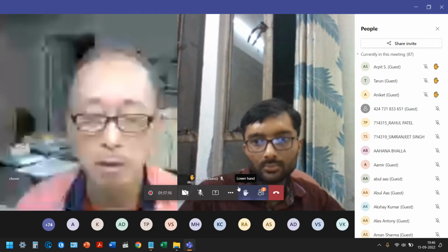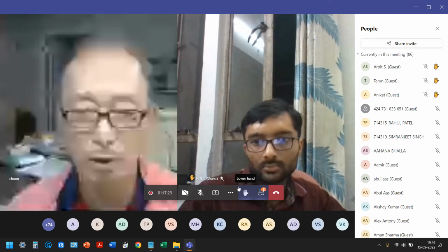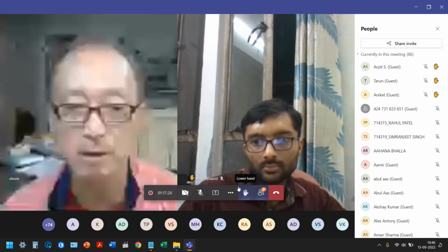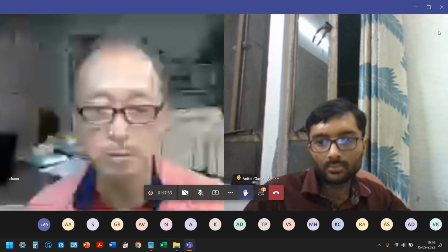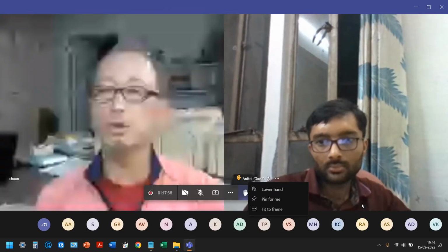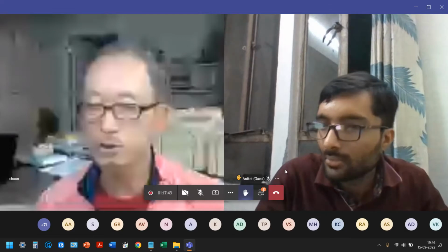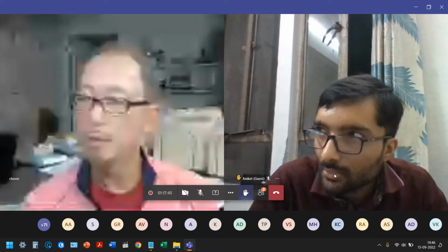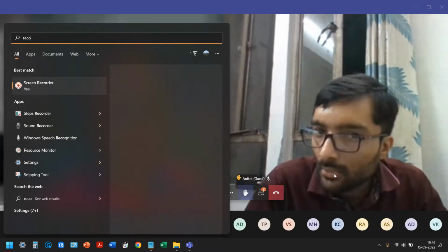According to you, what is the confidence in imaging structures shallower than 10 meters using MASW? I understand that we need a lot of high frequencies for this to happen, but high frequencies are typically noisy and contaminated by the presence of higher order modes. So answering number one, to deal with the shallow depths, you indicated shallower than 10 meters is shallow, but it is indeed the most common depth range nowadays dealt with by MASW.